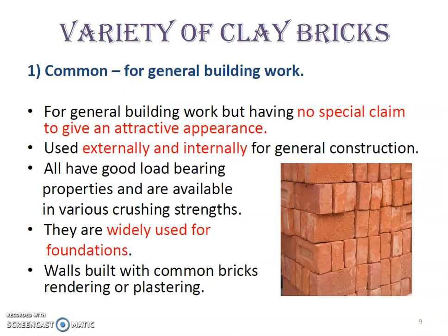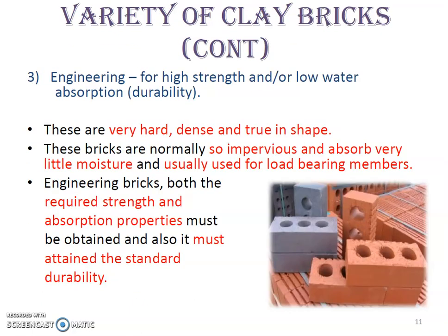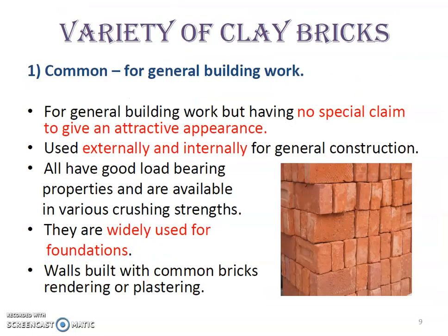We have three varieties of clay brick, which are common, facing and also engineering. Common clay bricks are used for general building works. These common clay bricks are not attractive, so they must undergo a certain process, which is rendering or plastering. They are widely used for foundations and also for external and internal general construction.